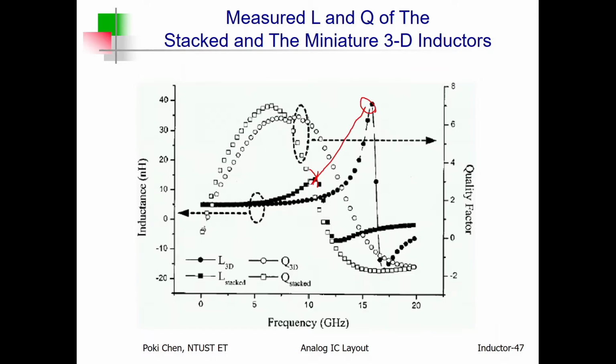You need to be careful after self-resonance frequency. Here it is inductor. After that, it becomes a capacitor. Okay, so it means what? 3D inductor can survive to much higher operation frequency than the stacked one. Wow, it's really amazing. It's really amazing.